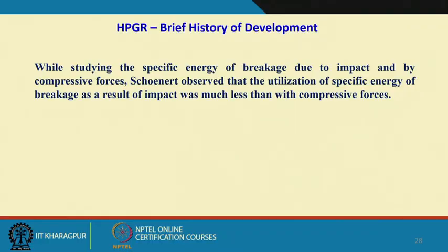It is a very big observation. The specific energy of breakage which is being utilized by the material for the desired fragmentation, with one group of machines using impact force and another group of machines using compressive forces, was observed to be much less with impact forces than with compressive forces, and that gave him the idea of how we can use the compressive forces much more effectively.